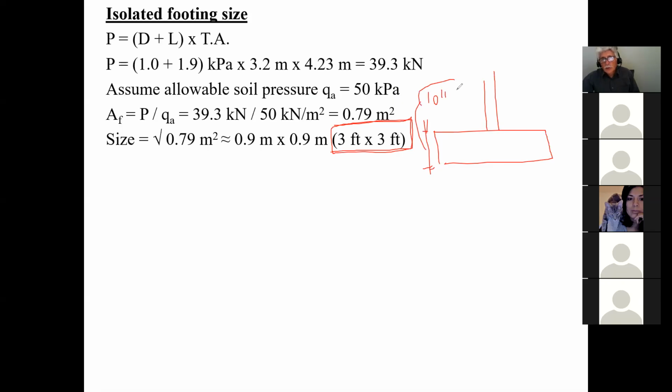But I would actually check to make sure that I can do this without any reinforcement, or I would design it as a reinforced footing just like I did, confirm that 10 inches, and then specify the reinforcement on my drawing. So I would either design it as a plain, in other words unreinforced, footing or as a reinforced footing, either way, but it would have to be designed.